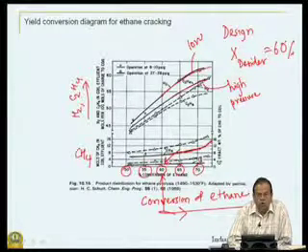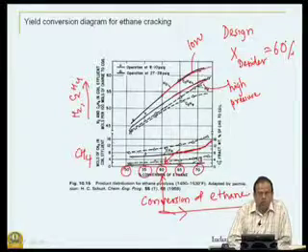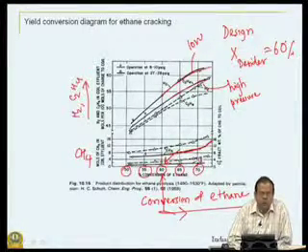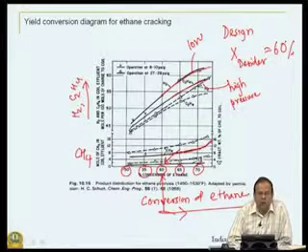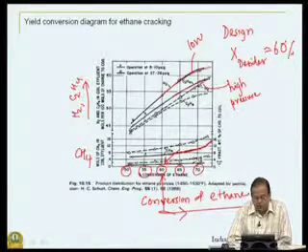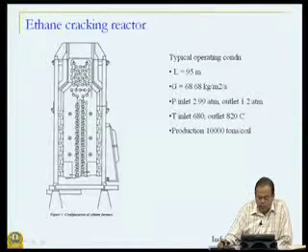You can't have very low pressures. For example, can you do this reaction under vacuum, just for the sake of argument? No, because low pressures for gaseous reactions also mean low concentrations, which means low rates of reaction. So, one has to strike a balance between higher pressure for higher rates of reaction and lower pressure for higher equilibrium conversions. So, pressure is also an important factor.